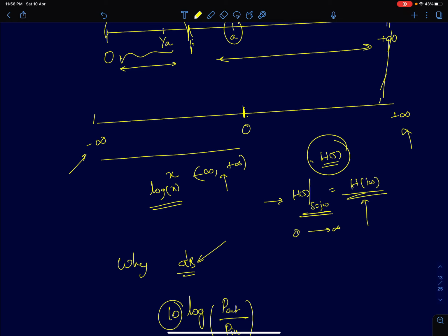The next thing is to draw the frequency response. As an engineer, given a transfer function, we should be able to have an intuitive understanding of how the frequency response will look. And similarly, if a frequency response graph is given, we should be able to read that graph as well. And we said one very important point: to draw this frequency response, where the frequency is going to vary from almost 0 till infinity, and amplitude can also have large variations, we resort to logarithmic functions.